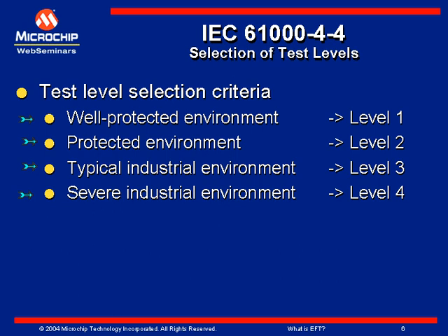And the fourth one is a severe industrial environment. The installation is considered to have no suppression of EFT bursts in the power supply and control circuitry, no separation of industrial circuits from other circuits, no separation between power supply and control signal and communication cables, and use of multi-core cables in common for control and signal lines. This is one of the worst environments; the outdoor area of industrial process equipment may fall in this category. Now, as per my experience, most customers go for either level 3 or level 4 compliance. That's the typical trend I have seen in various industries.